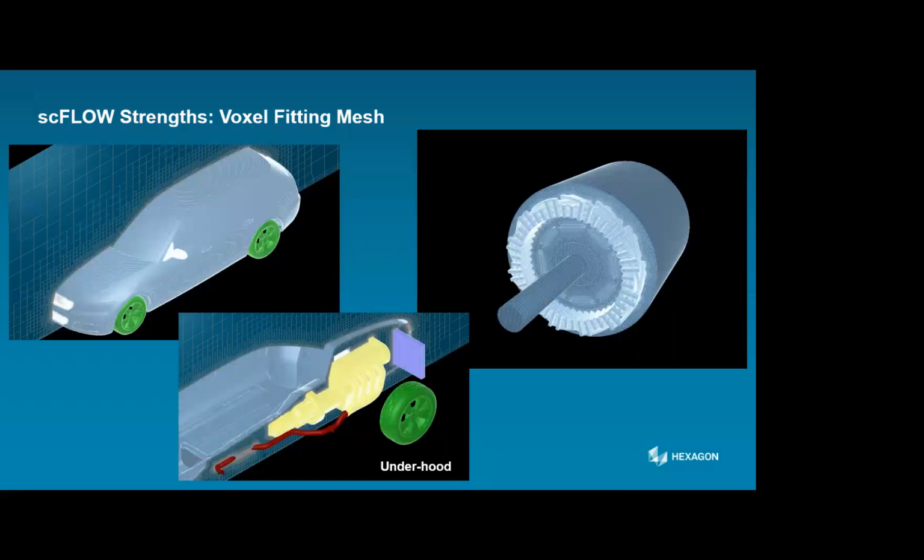SCFlow has a lot of key features, but some in particular are exactly what's needed for e-motor simulation. E-motors are very complex machines made of a lot of different components with a lot of details that must be considered in order to provide a more accurate and realistic simulation. SCFlow uses by default the polyhedral type mesh for domain discretization, which is very accurate and suitable for most applications.